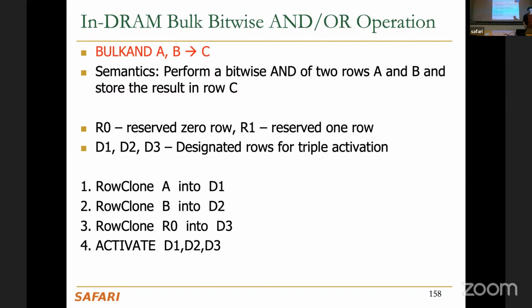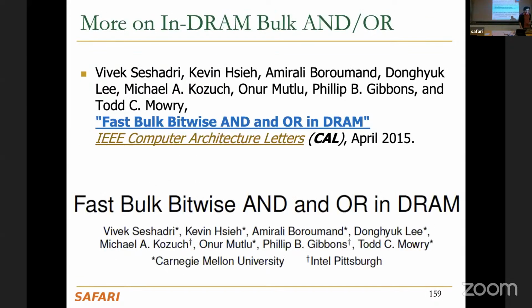So that's why the Ambit paper proposes to use RowClone to copy data from the source rows to some destination rows that are these designated rows or compute capable rows that I just mentioned, because you don't want to destroy all the data every time you use it. So first of all, you copy using RowClone from one source row to the compute rows, then you compute, and at some point you write back the results somewhere else to a different destination row. In this case, it's called C.